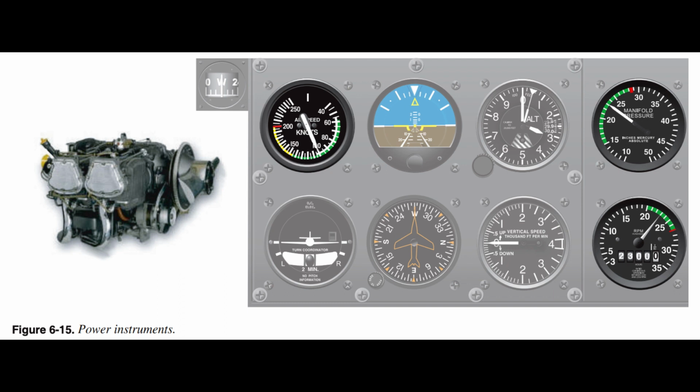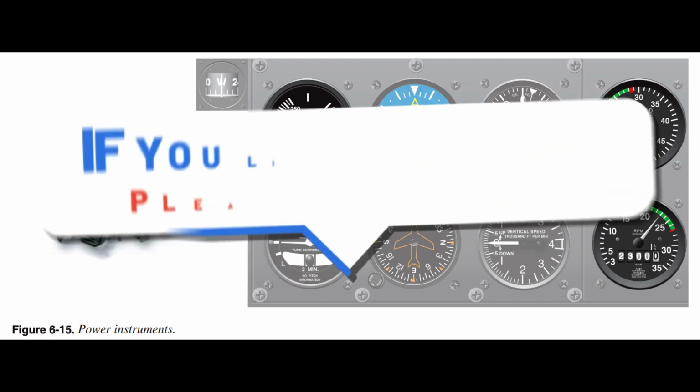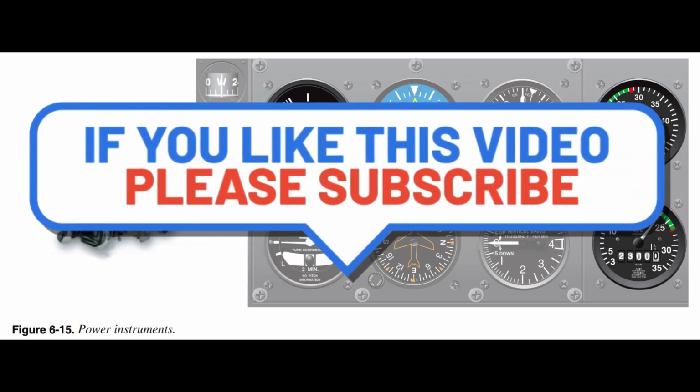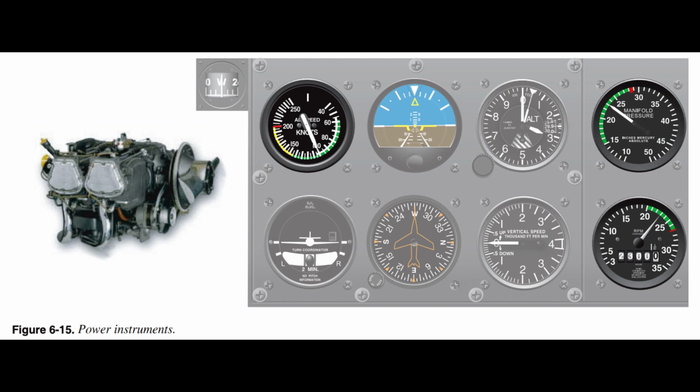Engine instruments. Engine instruments, such as the manifold pressure (MP) indicator, provide an indication of aircraft performance for a given setting under stable conditions. If the power conditions are changed, as reflected in the respective engine instrument readings, there is an effect upon the aircraft performance, either an increase or decrease of airspeed. When the propeller rotational speed, revolutions per minute (RPM), as viewed on a tachometer, is increased or decreased on fixed-pitch propellers, the performance of the aircraft reflects a gain or loss of airspeed as well.